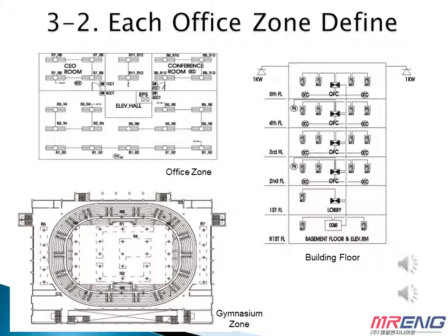The 1st floor and basement is configured with 12 relay zones. Due to the security lighting on the 5th floor, an additional zone is needed, as well as 13 relays as opposed to 12. Basement to 5th floor needs 1 LCP 12, and again the 5th floor needs an additional relay.